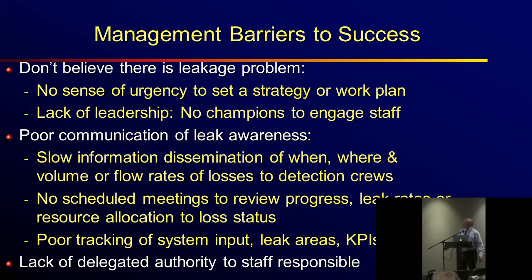This is the management part. I'm going to stick management here for a minute because the management, it's just not all about operations. Now, I've managed 3 water utilities in several provinces. Systems that have high leakage, management doesn't believe there's a leakage problem. You got to put it in their face. You got to do a standard water balance. You talk about the value of the water that's lost to get their attention.